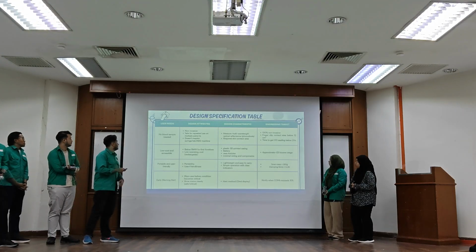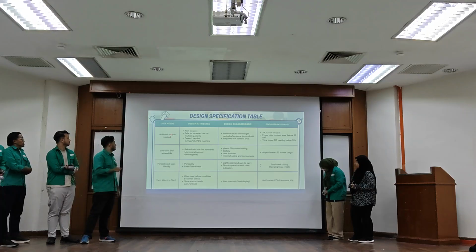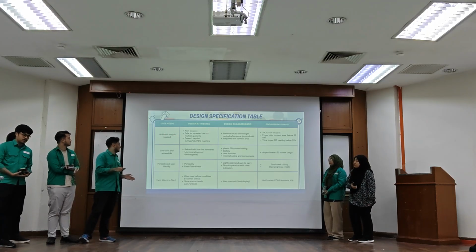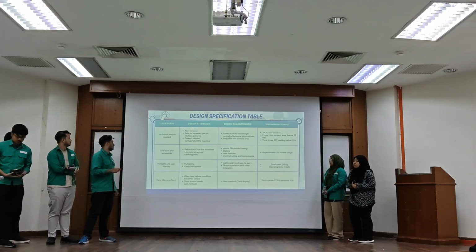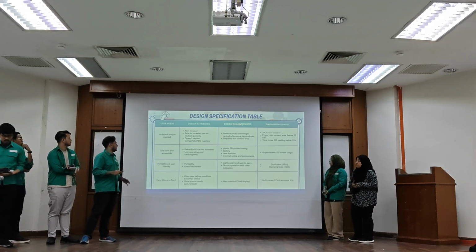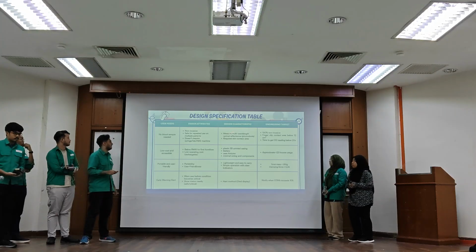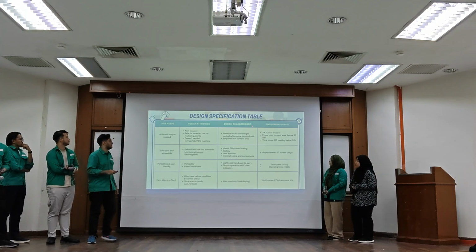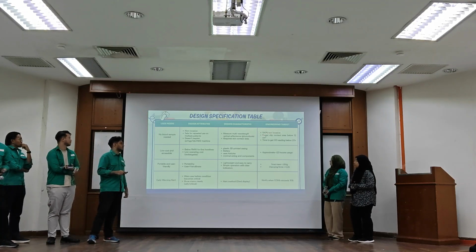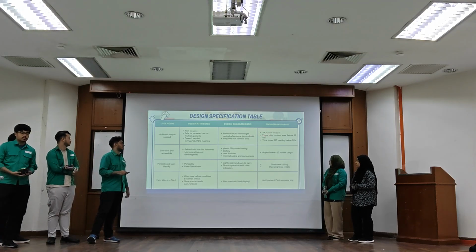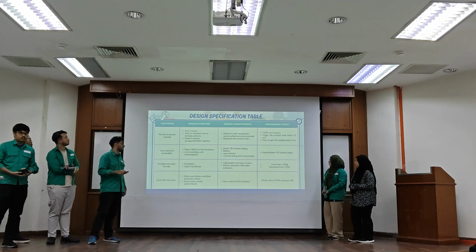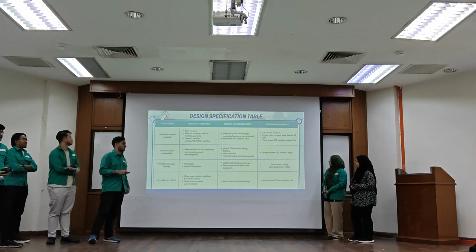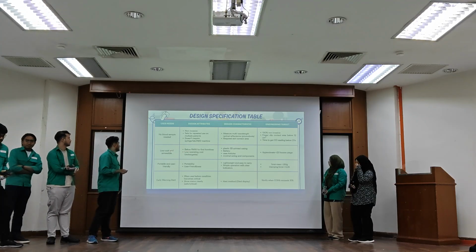So, design specification, first of all, our user need: we don't need any blood sample. In other words, it's non-invasive. So how do we achieve non-invasive? We need to use multi-wavelength light, which requires a skin contact area. Our engineering targets for this are, first, 100% non-invasive; second, the fingertip contact needs to be below 12 centimeter square; and we also need to read the CO in below 20 seconds.